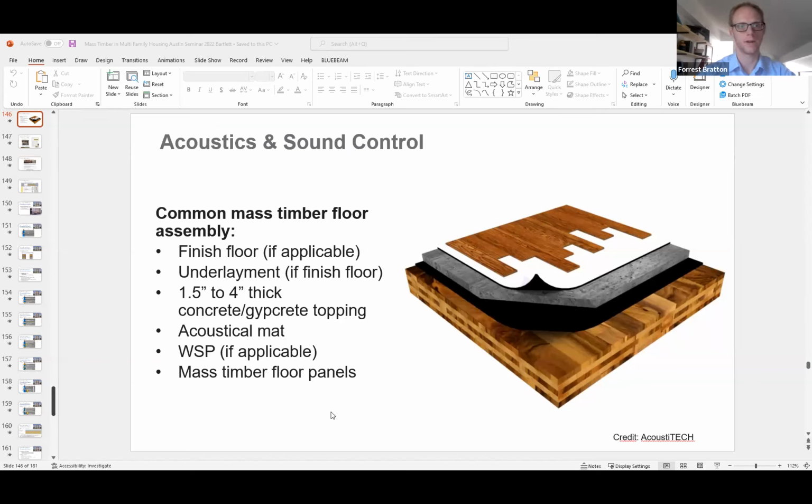So we had to keep it lighter than that, and so that ended up being a lot more to consider. And when they went back and tried to reduce the costs of the buildup we had originally started with, it was a lot of how do we get there again with the maximum. We had a 12 pounds per square foot limit on the weight it could be. Most of these poured toppings start out at 19-20 pounds a square foot and go up from there. If you've got several inches of concrete, you could be a couple times that. So just another challenge to think through.